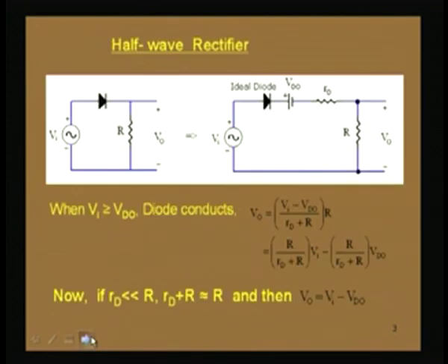For this rectifier circuit, we use the semiconductor diode which we have discussed earlier. First of all, let us discuss the half wave rectifier. This half wave rectifier circuit converts the AC voltage to a unipolar DC voltage, but only one half of the input AC voltage will be available, and in the other half we will get 0 voltage.